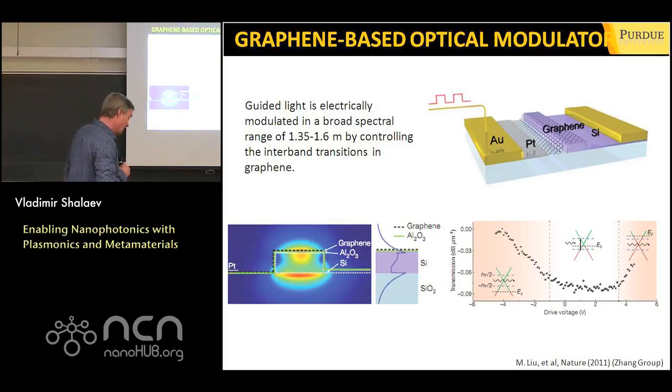In that regard, of course, silicon waveguides might be a good idea to use. So basically you do all this switching and processing on the nanoscale using plasmonic structures, but propagate using silicon wires, as sometimes they call them, but they're wires for light rather than for electrons. And the idea in this particular case, how to make a modulator out of this silicon wire, is to put graphene right on top of the silicon waveguide. And if you look at the field distribution in this silicon waveguide, it's actually concentrated largely right in the area where graphene is. So why is it important?